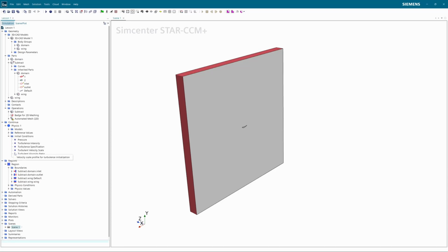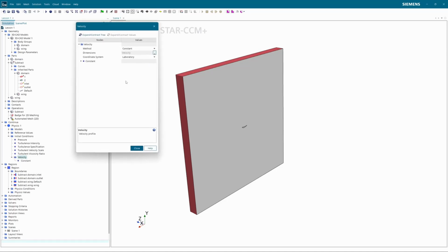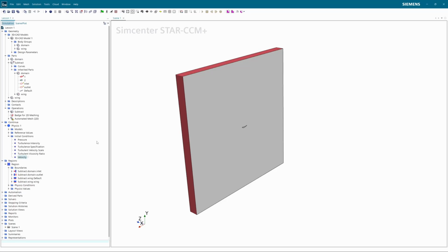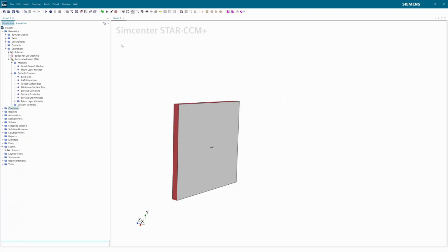So, very important, you can press this velocity and go to a constant, and we will set this to minus, we could set it to 15, but in general, putting it a bit lower creates a slightly more efficient system where your simulation will converge a little faster. So we go to minus 14 meters per second. That will add the initial conditions.